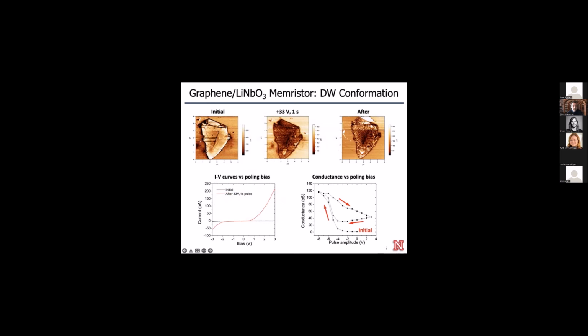So this approach actually allows us to alleviate a problem associated with high leakage of the device after it is set in the polydomain state. If you have highly conducting domain walls, the switching of polarization in this device becomes difficult. And it will also not be very beneficial from the viewpoint of power usage. So the approach that we use here, using the subcoercive voltage, provides significant improvement in terms of energy cost, resilience, lifetime, and also controllability of the resistance states.